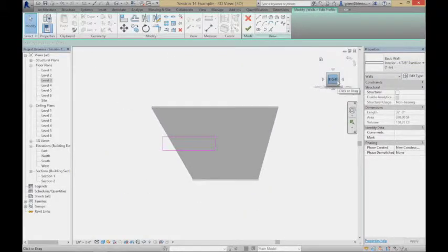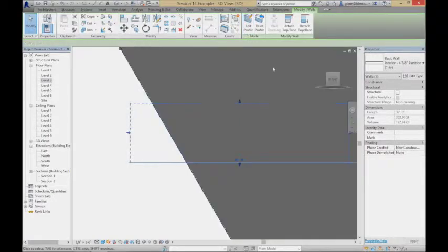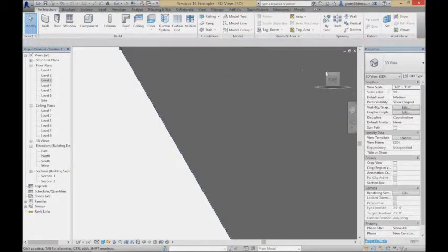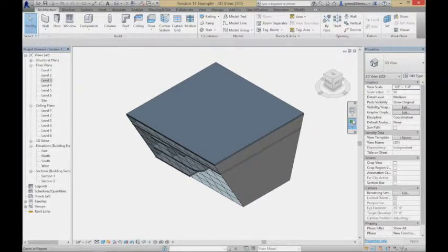Let me switch it over to the right so we're looking at it dead on. Okay, and now I can go through and basically pick that surface. Trim. So this is just using that wall profile stuff that we learned very early in the class. I'll finish that up. And now when we go popping back over there, the wall will look really good.